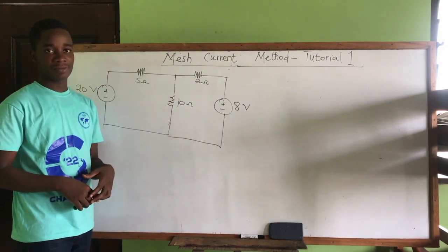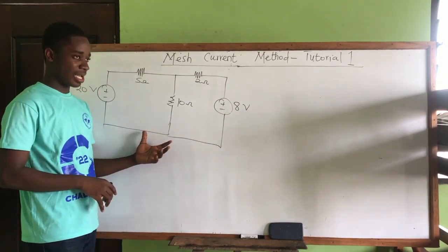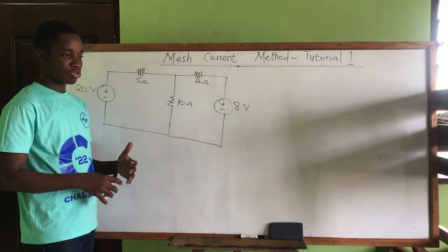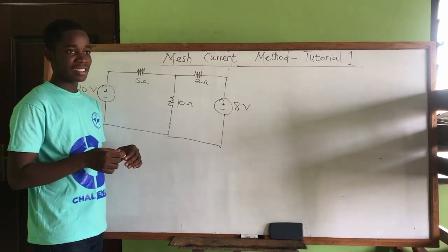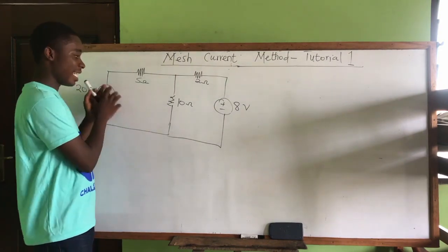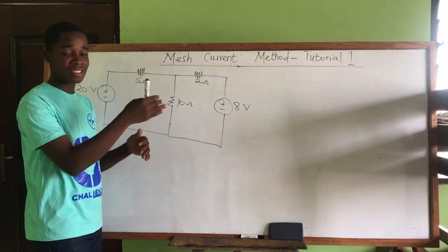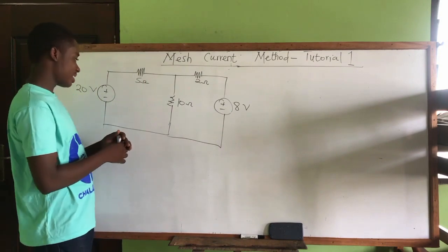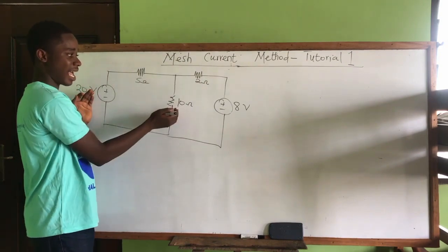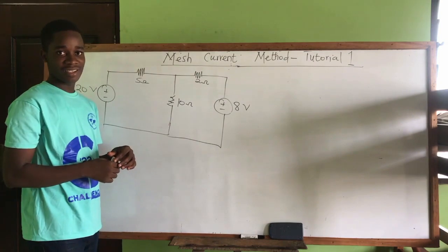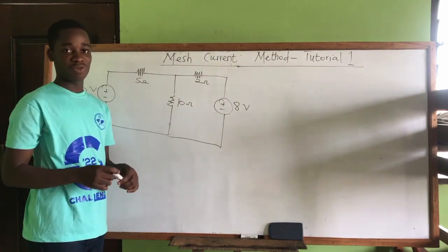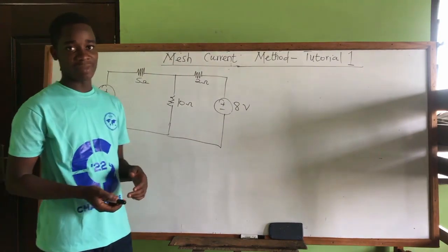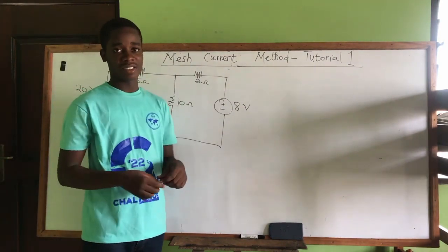all the resistors. In this diagram, we can't straightforwardly use the network reduction, the series parallel, because the sources are 2. If you have a circuit and there is only one source, either at the end or inside the circuit, then we can use the series parallel combination. But we have 2 sources, so we can't say we are standing here and say this and this are in parallel while there is another source there. So we can't use the network reduction approach we've done so far in this circuit. So we are going to use the mesh current method to find current in all the resistors here.